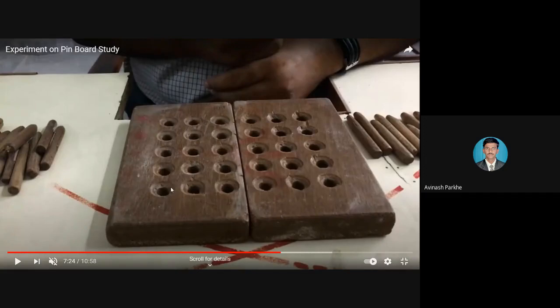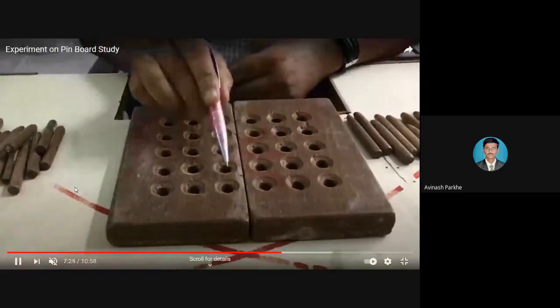Due to the bevel holes, whenever I am inserting the pins in the holes, the pin can be inserted immediately and your time will get saved. In the previous also, the time decreases, but the straight holes create the problem. The pin is not properly inserted, but due to these bevel holes, or this extra diameter at the top side, the pin can be inserted immediately and your time will get saved. Now you can see how much time will get saved.